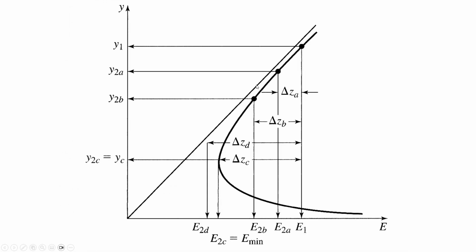So here's our specific energy diagram that was showing each of those 4 cases. Like when we had a small step height, a little bit larger of a step height, and how the depth got shallower downstream from that.